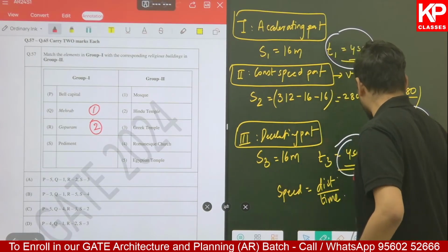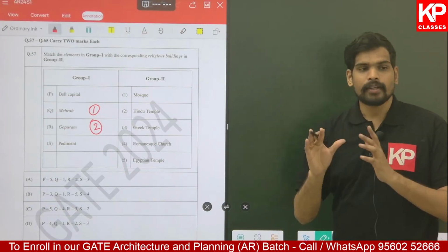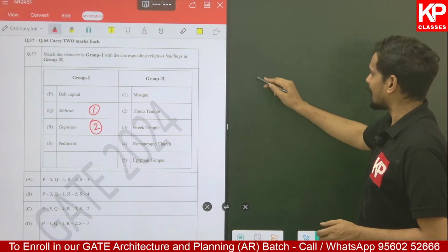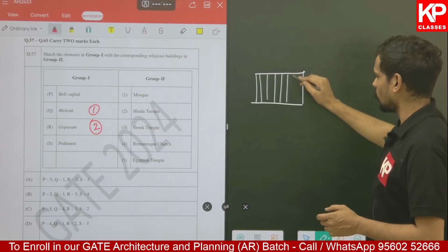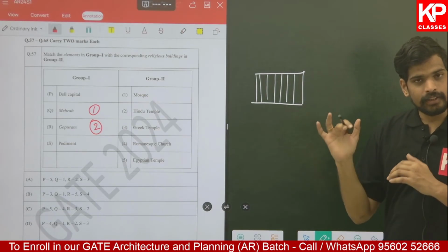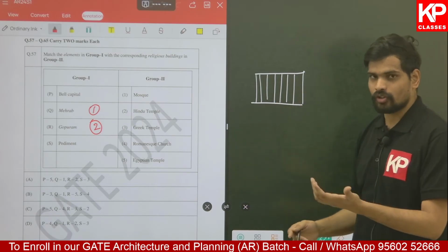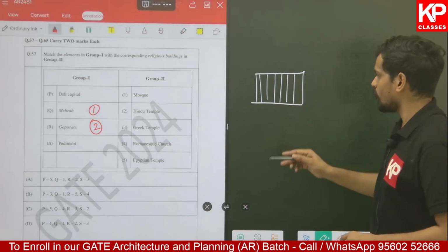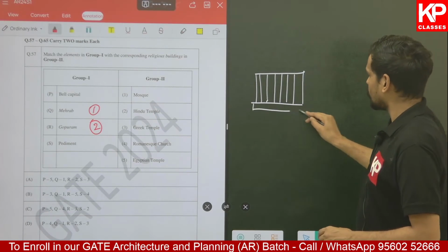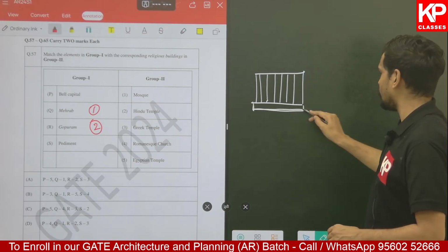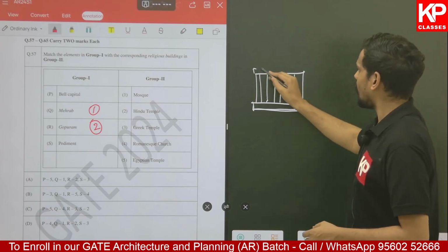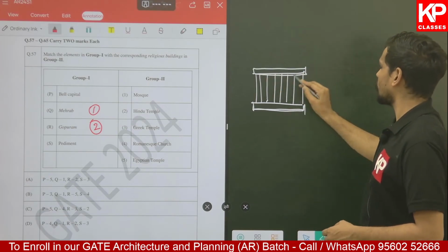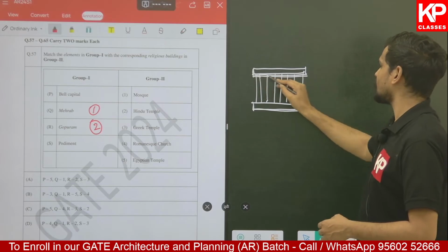What is pediment in Greek temple architecture? So in a typical Greek temple, also in Roman temple, in the classical architecture, you have temple facade where you have columns, the classical order columns of Doric, Ionic, Corinthian, Tuscan or composite order based on which style it is, Greek and Roman both. In Greek temples typically you have a plinth which is called crepidoma, which includes stylobate and stereobate. Then you have entablature on top of the columns, which includes the frieze, the cornice, and also say